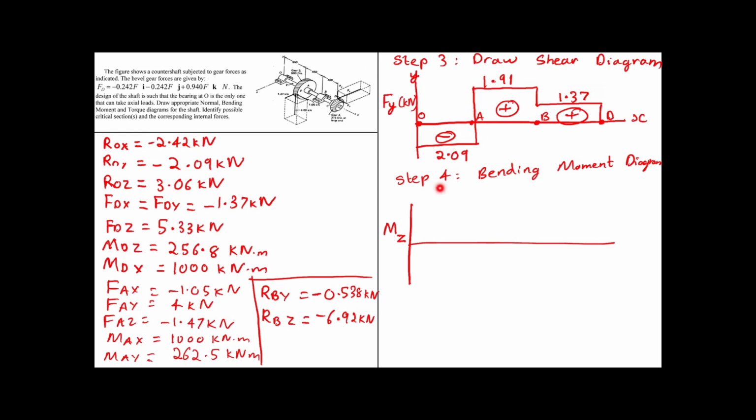This makes sense because the z is like coming out from this point. So any force would create a moment about z-axis. So if you draw the shear diagram for xy plane, the moment diagram would be for the z axis. So the area under this graph would give you the value of moment at point A.